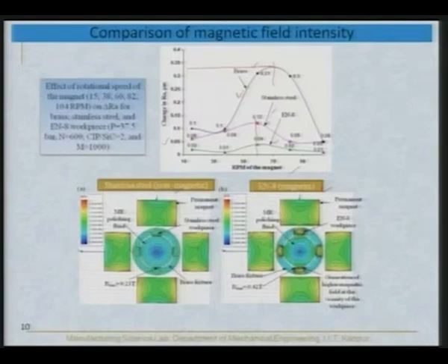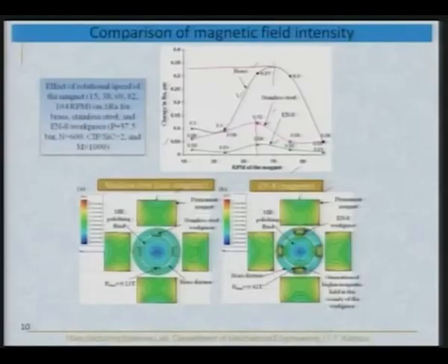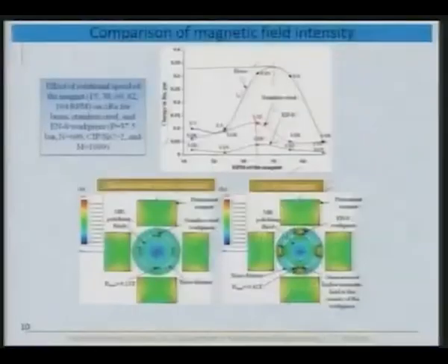So, you will not get uniform finishing, and also some of the magnetic particles may get attracted by so large a force near the magnetic material that the finishing rate will reduce substantially.